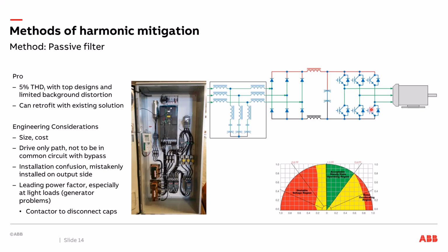And then the last thing, and this is really important for systems that have backup generators, so hospitals, data centers, laboratory environments, airports, is you have to be careful with leading power factor because backup generators do not like leading power factor, and the capacitors in the LCL circuit really do generate a leading power factor at partial load.